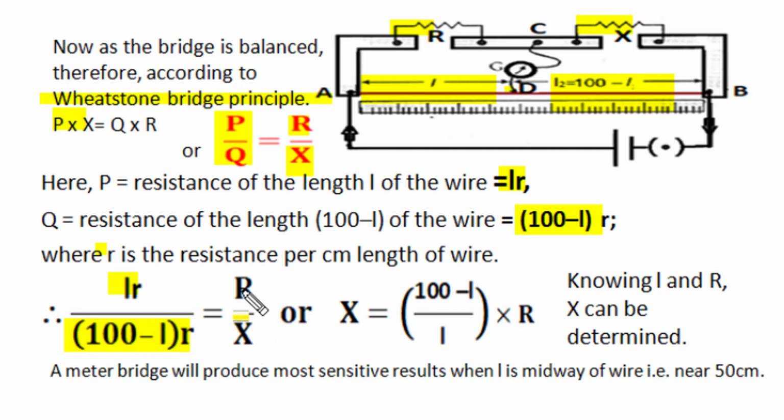So we can make comparison of known resistance with unknown resistance without knowing the per unit resistance value of this slide wire. The only requirement is that all through the length, the per unit length resistance should remain the same, and for that the wire should be of the same resistivity all through the length, and it should have the same uniform cross-section area all over the length. Now this relation can be modified as: unknown resistance is equal to known resistance multiplied by (100 minus L) length divided by L length.